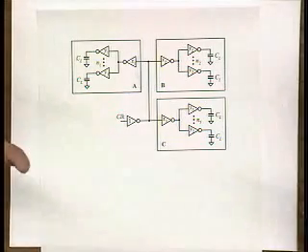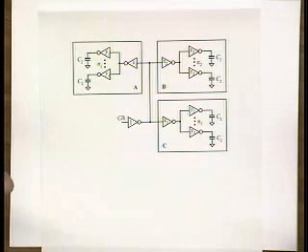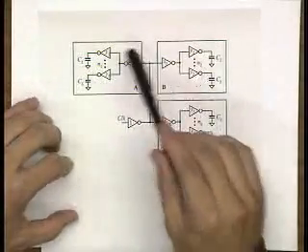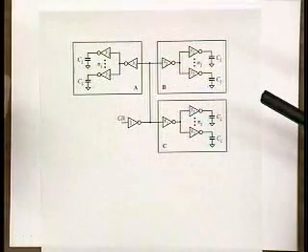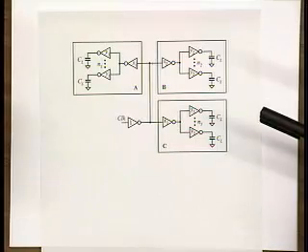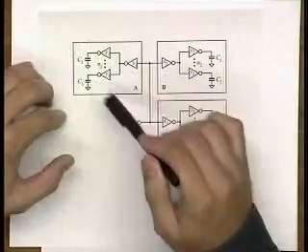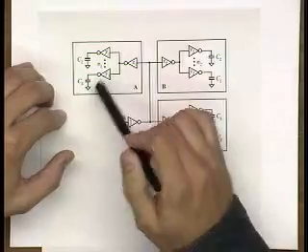So here's what it's all about. Basically, you assume that you are designing a large system. And in order to deal with a large system, as we hinted so far, it's a good idea to do hierarchical design and figure out design blocks A, B, and C. Since chances are that these design blocks will have different complexity, in order to distribute a clock tree, you would have to see a different clock load in each of these domains, which is represented by the number of these parallel branches that you have in each of these domains.